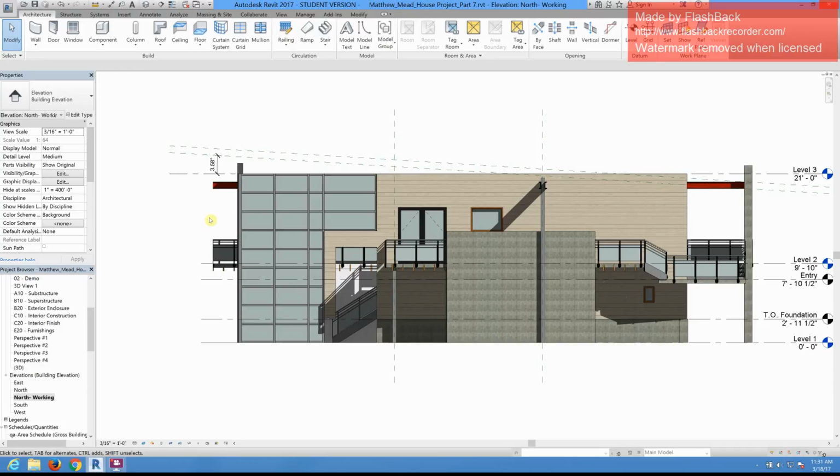But if you don't, maybe you weren't here last class, you're going to have to click on beam and upload that 2x10 piece of lumber prior to starting the beam system. Okay, so what it's telling you is, if you scroll down a little further, I think it tells you to offset the first beam system by 1 foot.